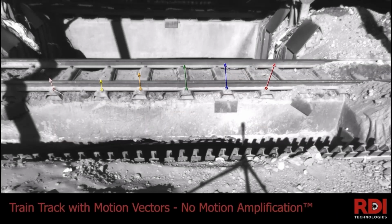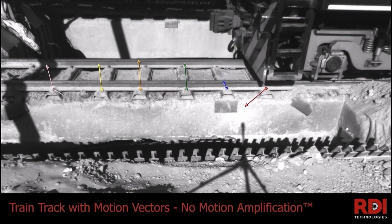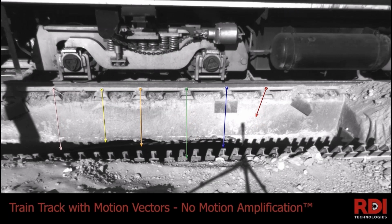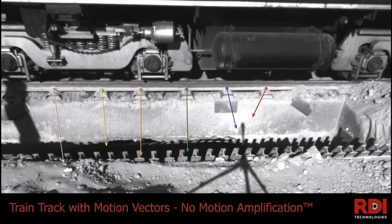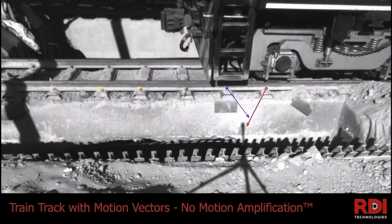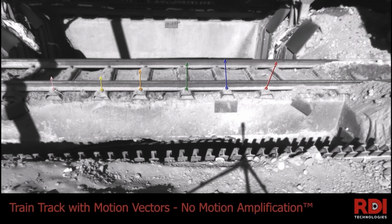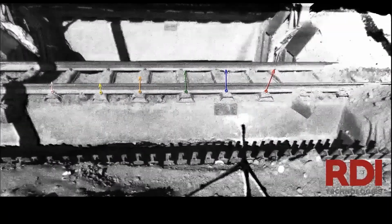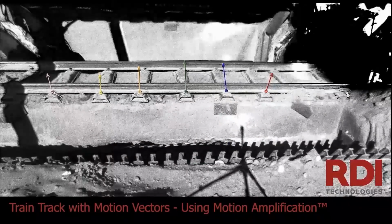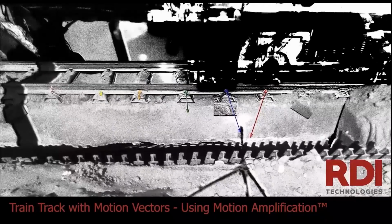And then here is a rail car moving. And what I like about this, you can see the vectors progressively go down, as that goes in that direction, right? And so it's pretty interesting to be able to see the motion and the way that responds. Again, no amplification, right? And it's also interesting to see them go up like that, because when that train comes on and actually forces it down on the right, it sort of bows up, forces the rail up on the left-hand side. So again, just really easy to distill it down. Here's with motion amplification. You can actually see the track kind of depressed there as that train comes through.